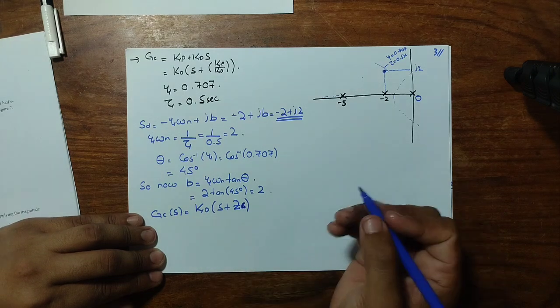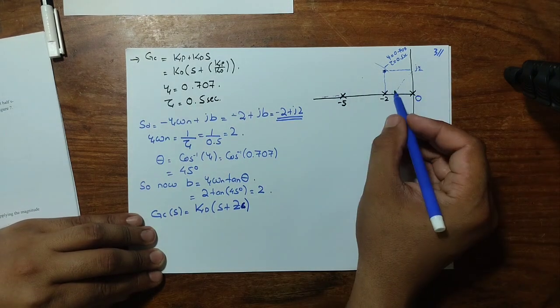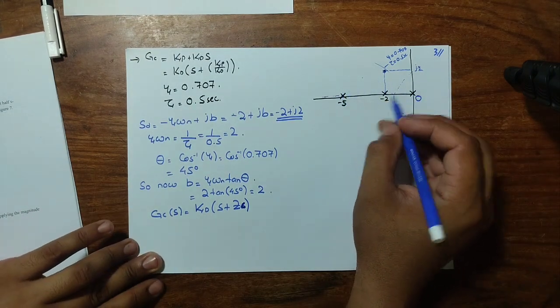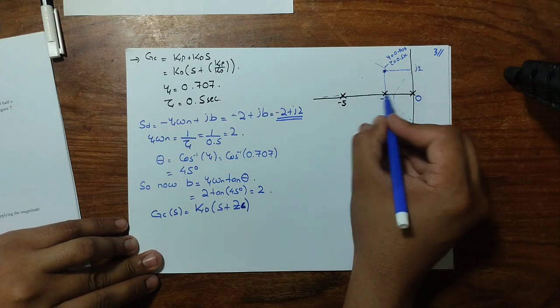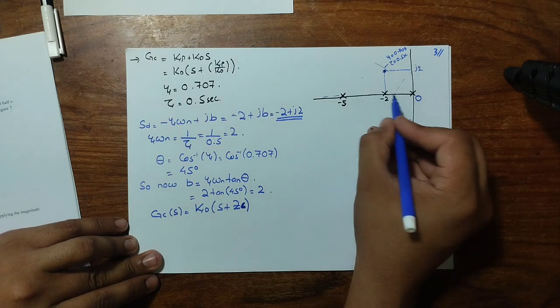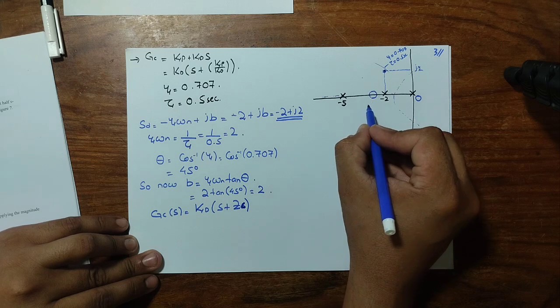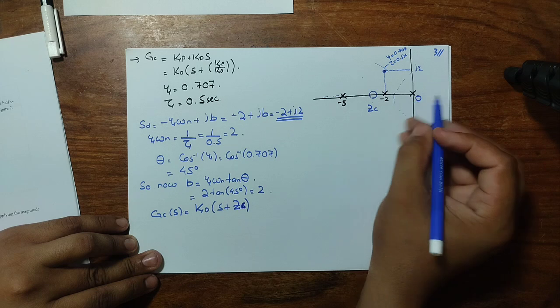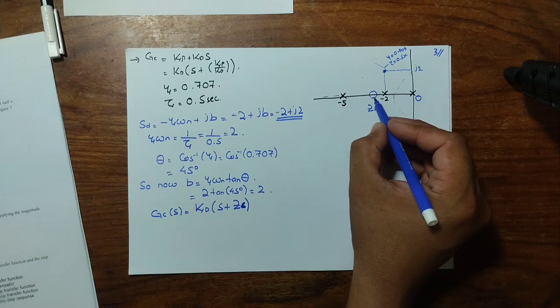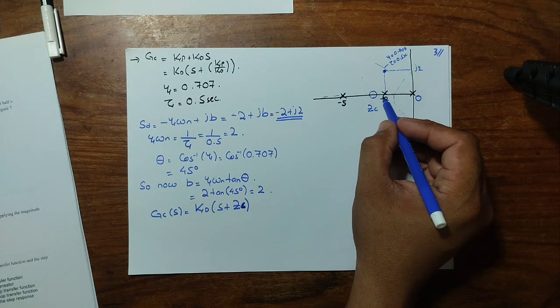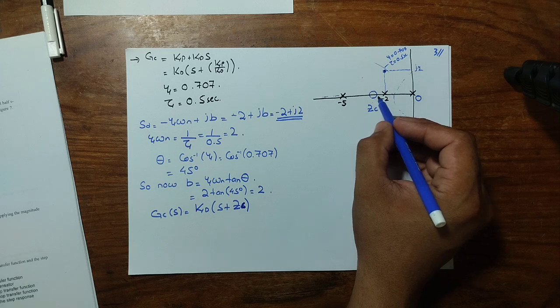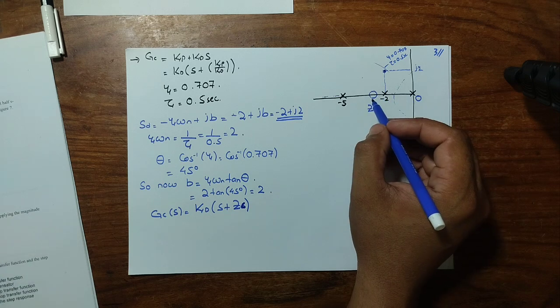We have to arrange it somewhere in this S plane so that the root locus shifts to the left half plane. Randomly, you can place it anywhere because we can readjust based upon our calculation. So for the instant, I'm placing it here. This is ZC. Again, I'm assuming this position. You can assume it anywhere in the S plane, because at the end, when we calculate the values, we will see that it may change on the real plane.